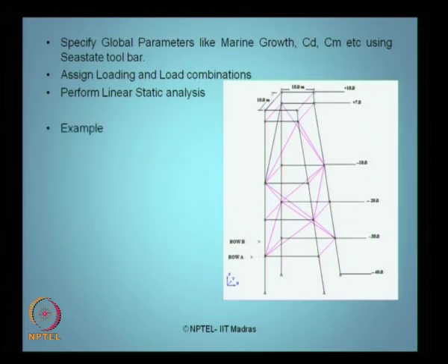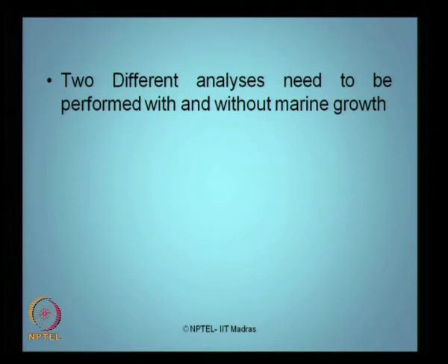So, the example structure what you see here on the right is what you will see on the screen once you follow all the above steps to do the linear static analysis. Subsequently, two different analyses need to be carried out or performed for this kind of structures. One is without marine growth and one is with the marine growth.